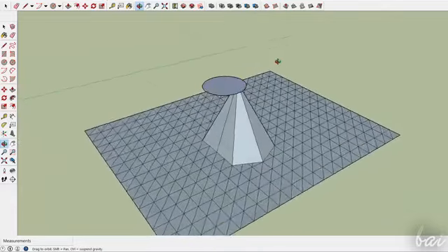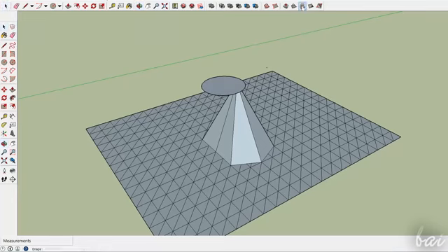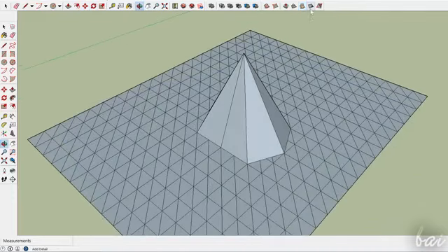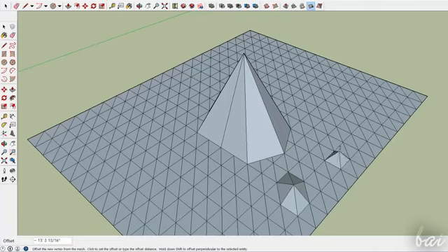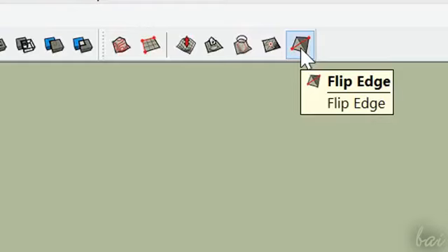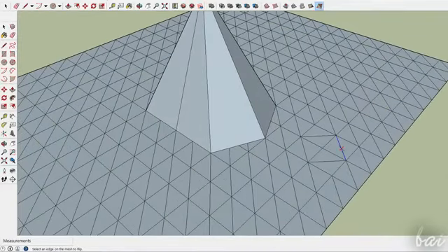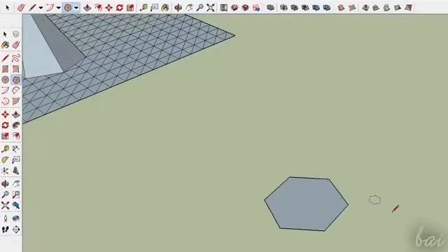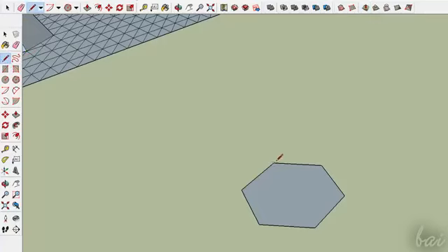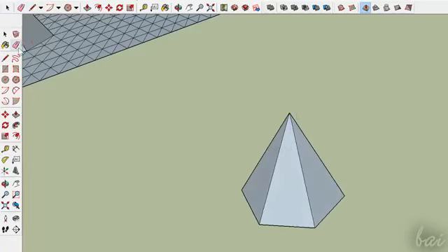Drape is used to paste on your mesh a shadow contour created by an object that stays above. Use Add Detail on triangular sides to add more lines, whereas use Flip Edge to flip the side's direction. In this way, you can edit your sandbox better. Mind that the sandbox tools do also work on objects that are not related to mesh objects. For example, it is quite fast to create a pyramid using the Smooth tool on a polygon.